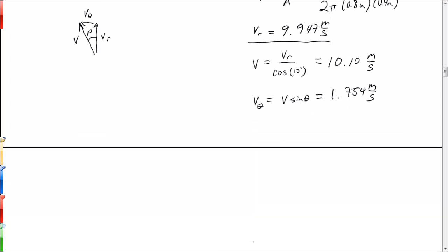The torque is given as the integral over the control surface of rho times r crossed with v times v dotted with n hat integrated over our area. At the inlet, we know that the flow is entirely radial, so the r cross v term evaluates identically to 0. So we only need to evaluate this at the outlet.